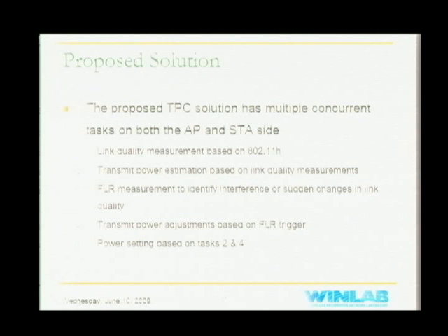By lowering the transmit power, we still guarantee that it's not just going to the smallest possible, minimum transmit power. As we already mentioned, the transmit power that is decided by RSSI measurements ensures a certain SNR. So it ensures a certain sensitivity for a target data rate. Say in our case, if negative 61 dBm is the sensitivity for 130 Mbps, then we don't reduce the transmit power so that it goes below negative 61 dBm.